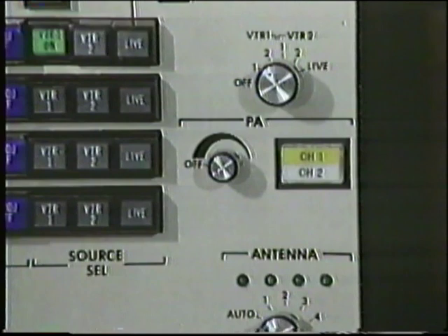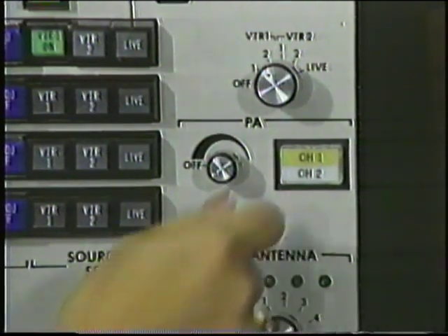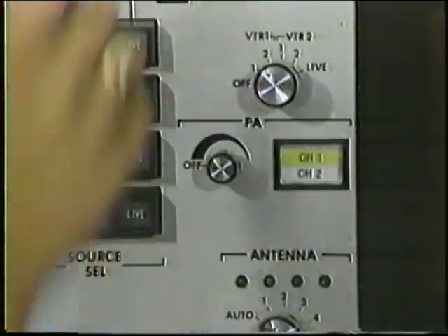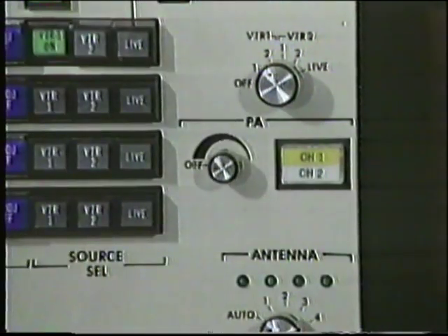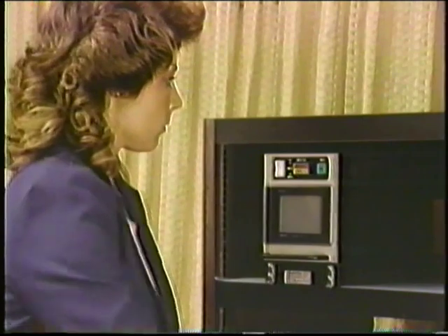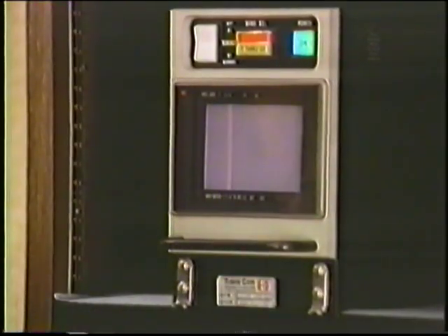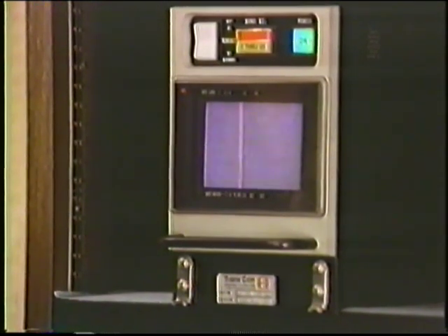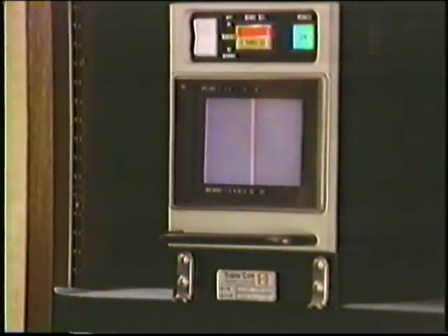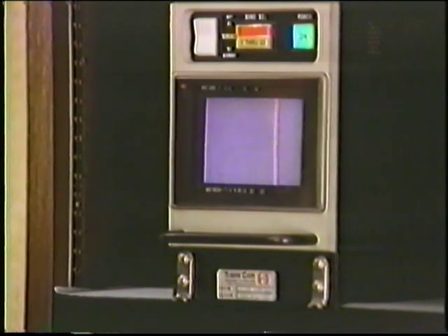The SCU includes a video system PA capability which channels audio over the PA system, such as when playing safety tapes. For movie viewing, set the PA speaker knob to the off position, full counterclockwise. If your aircraft is equipped with a 4-inch monitor, turn it on like this. Check that the monitor is on by seeing that the on button and the screen are illuminated.